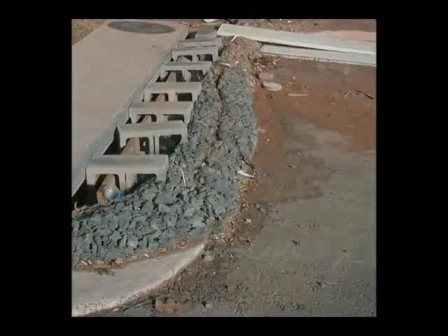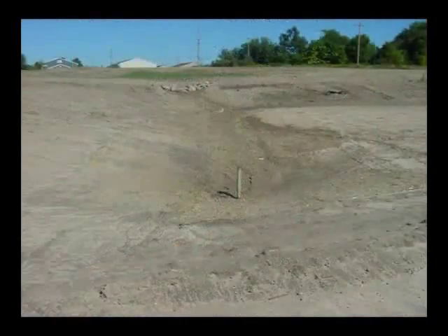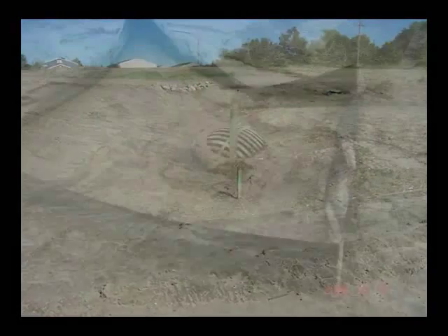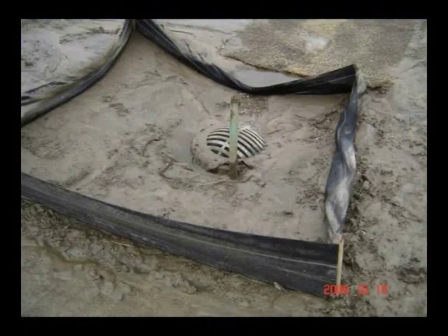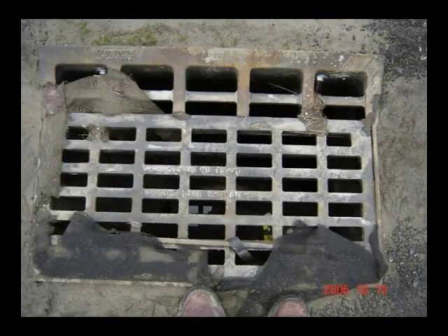Standard concrete building blocks or wire mesh are placed on the inside of the gravel filter to keep stones from being washed into the storm drain inlet. The configuration of the filter will depend upon the type of inlet being protected. The inspector needs to check for clogging of fabric or screens, overtopping, and structural integrity. In particular, ensure the structures are protected from and not damaged by vehicles.